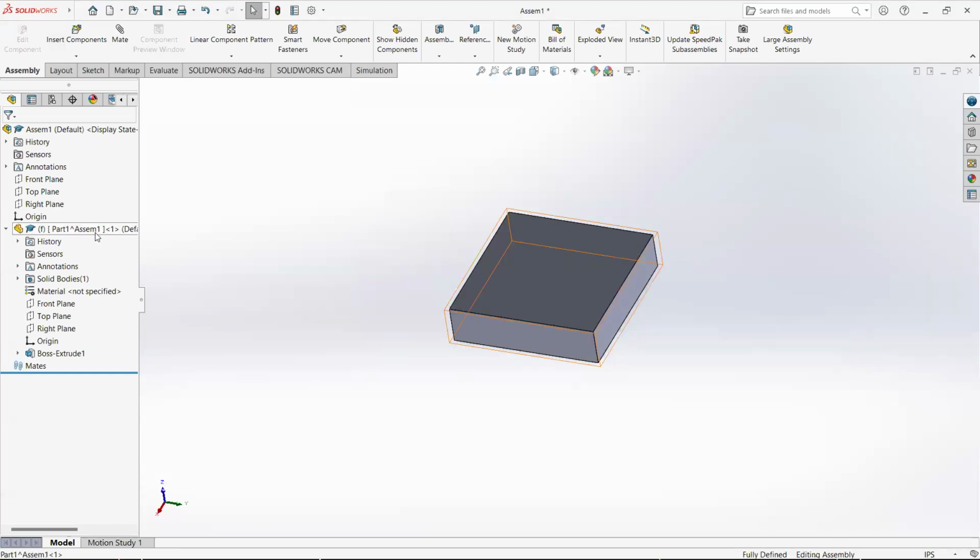I want to first, as I mentioned in previous assembly tutorials, we don't really like this fixed being here, because in this case, because I created it in the assembly, it is fixed. And if I highlight the origin of the part and the origin of the assembly, those are the same now because that's where I drew the part, right? I created it in this assembly using the assembly's axes. Best practice is to get rid of this fixed constraint.